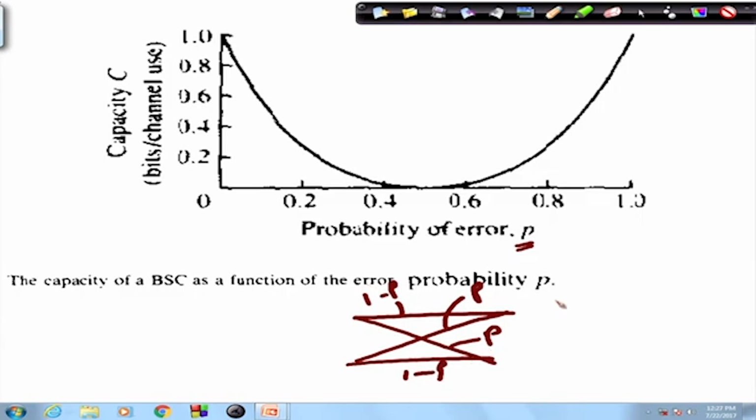So, that means a 0 remains a 0 with 50% probability and a 0 becomes a 1 with 50% probability, right. So, when I receive a 0, there is a 50-50 chance that a 0 was sent. In that case it is equiprobable whether a 0 was sent or a 1 was sent. So, I would make no special decision if I choose a 0 or a 1, right. So, that is the worst possible scenario. Now, if I know that a 0 is sent and the probability of it becoming 1 is, let us say, 10% only, then 90% of the time you can send signals successfully.